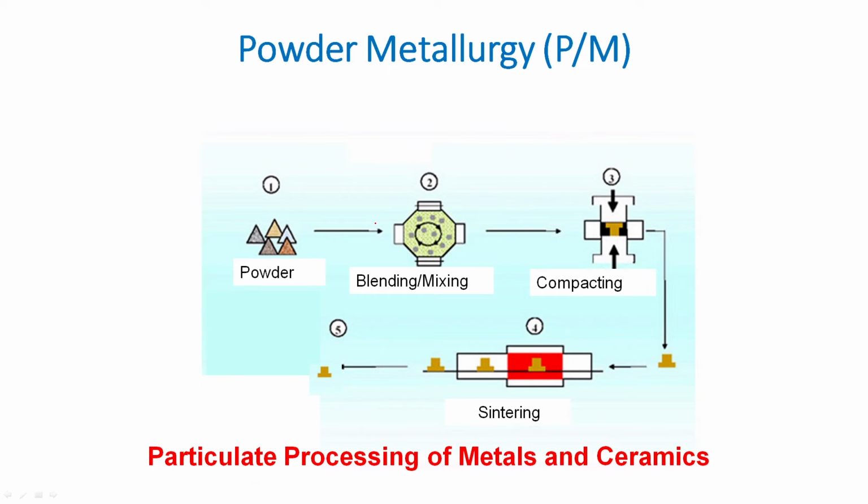Other than the strain rate, you remember that friction and lubrication is also an important factor in metal forming processes. You have to consider the frictional aspects very significantly, because we are using dies and punches, and in these contacts the friction is significantly high. So one uses lubricant to reduce the friction and the heat due to friction. So these are the 4 fundamental factors: stress, temperature, strain rate, friction and lubrication.